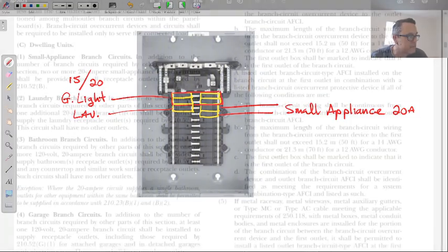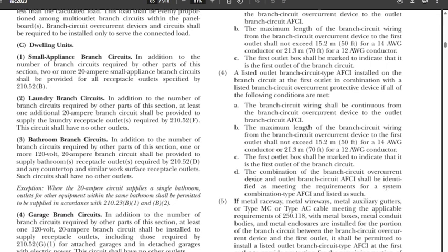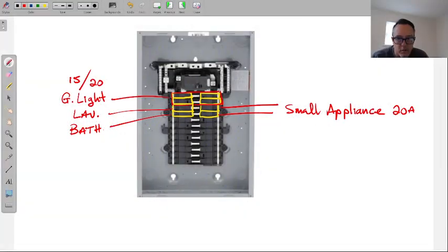All right, the next one is bathrooms. Same thing. The house will have a bathroom, sometimes 2. 1 breaker in the panel, 20 amps. And this one just went up. I don't know exactly when, but it used to be 15 was allowed for bathrooms. Now it's 20. And you have to have 1 circuit. Remember, this doesn't mean 1 outlet. I want to make that important note. This is 1 breaker in the panel representing the bathroom. This is the bathroom's representative.